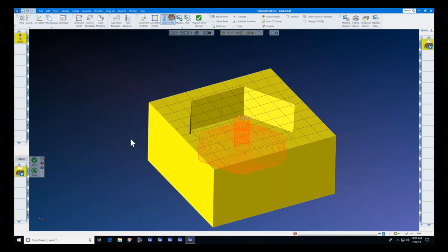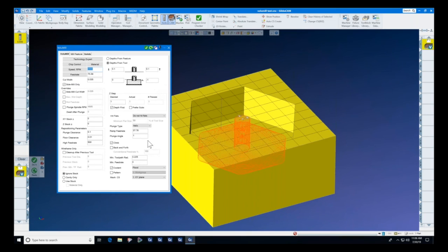Now, all this is leading up to this alarm that we're having, radius too small. And right here, we have minimum toolpath radius. We generally want to set your minimum toolpath radius to just below the radius of the tool, because by changing minimum toolpath radius, it allows us to get into tighter areas. And if we change this number to too small a number, it will say radius is too small.